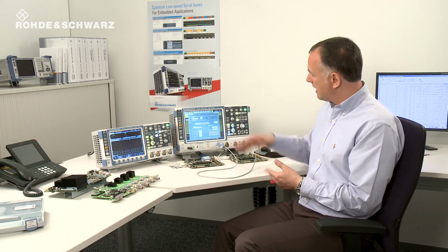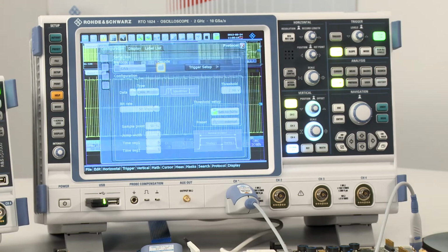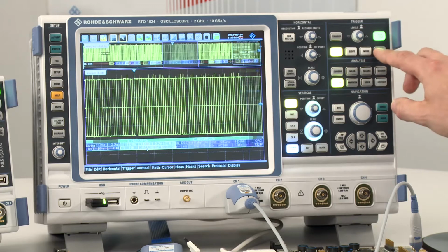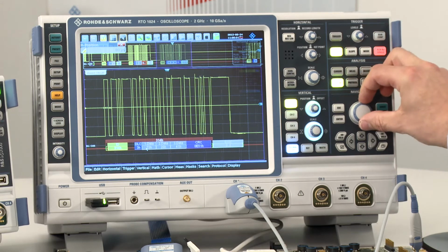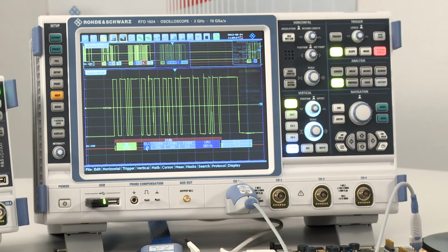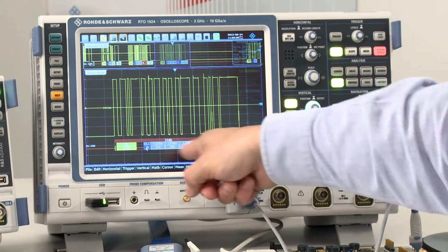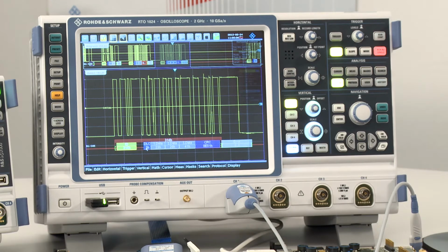Now, quite an important thing when you're decoding the data is the threshold. The threshold determines whether the data has been decoded correctly or not. In the threshold setup, we have a soft button which automatically sets the threshold to 50%. As soon as I press that button, in the background we can see the decoded data. I'm going to stop the acquisition for a second and move the zoom window around a single frame. There I can see the ID number, 314 hex, the data length code, the 3 packets of data associated with that code, the CRC, and in this case we have an error bit as well.